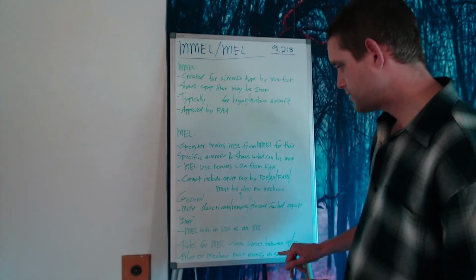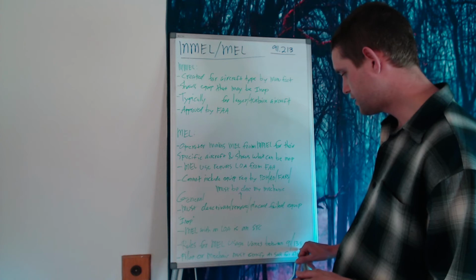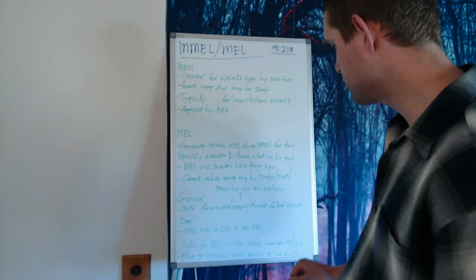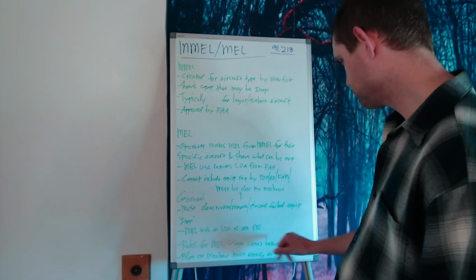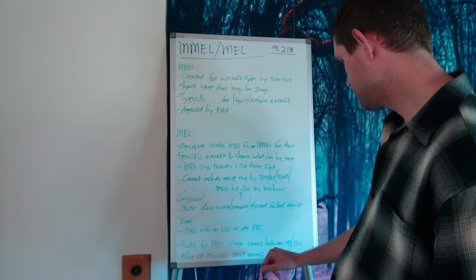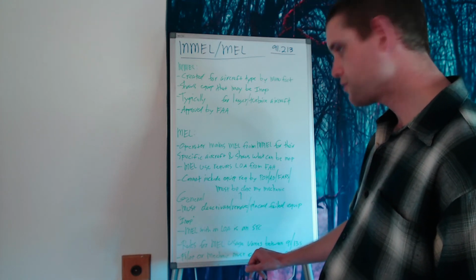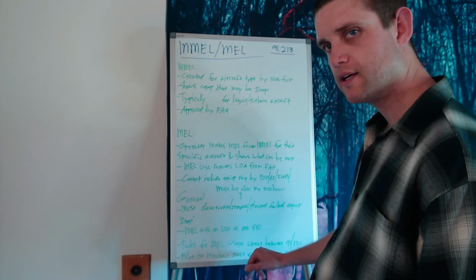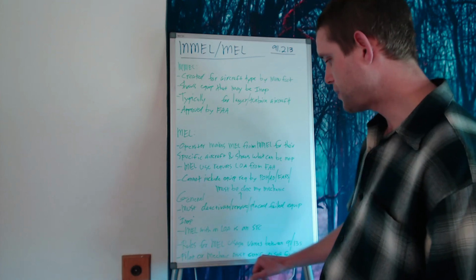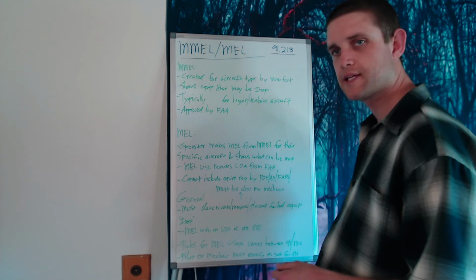The basic rules apply to Part 91 operations. For other operations such as Part 135, the rules differ and get a bit more complex. If you need to remove or disable a piece of equipment, you have to have a pilot or mechanic certify that the aircraft is still safe for flight at that point.